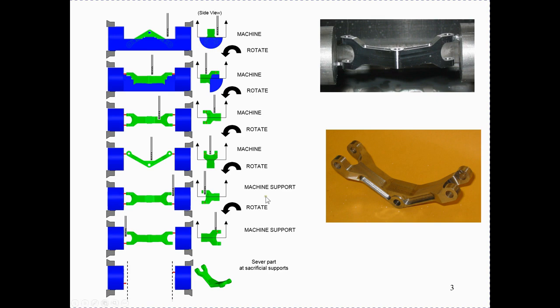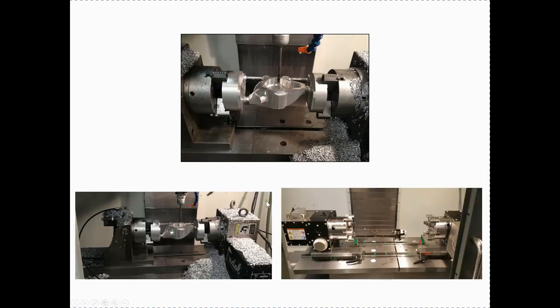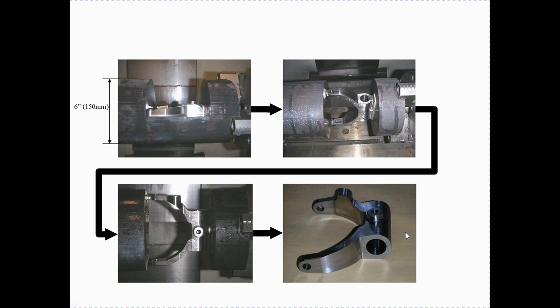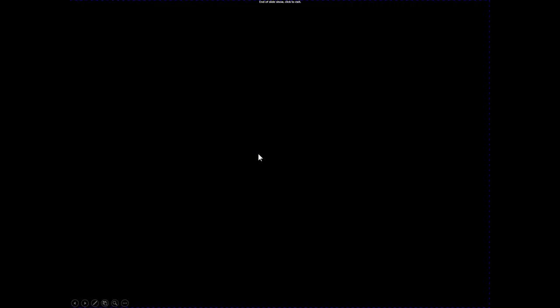and how to set up their machine. What this looks like is just inside a conventional CNC machine, a piece of round bar fixtured between jaw chucks. The minimum requirement is to run with a single rotary with a live tailstock and brake. The preferred setup would be dual rotaries. And what this looks like is after just a few minutes of process planning, we can cycle start and machine a part from a piece of bar stock. Next up, we'll take a look at the CNC-RP software.